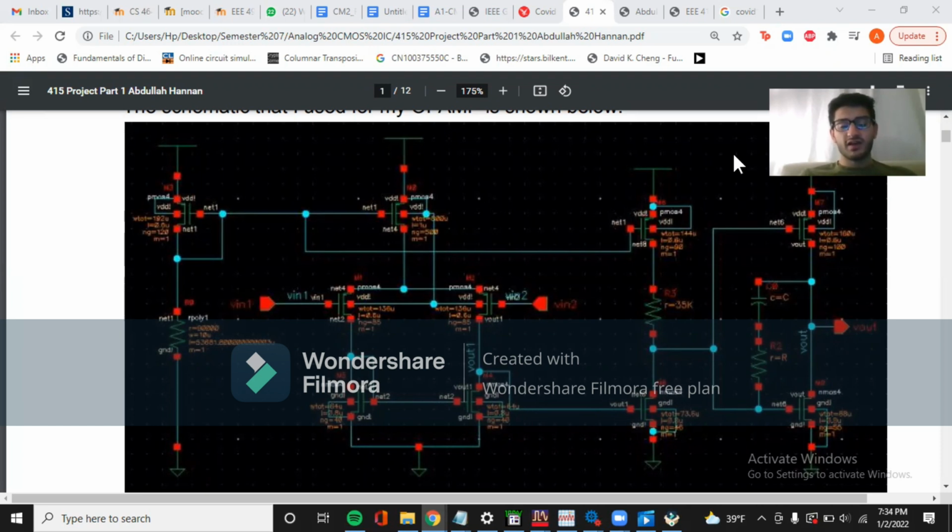Our project was to design an 8-bit digital to analog converter. The digital to analog converter comprised of two parts. The first one was an R2R ladder in voltage mode with a reference voltage of 4 volts, and the second one was an op amp, which was used in unity gain configuration.